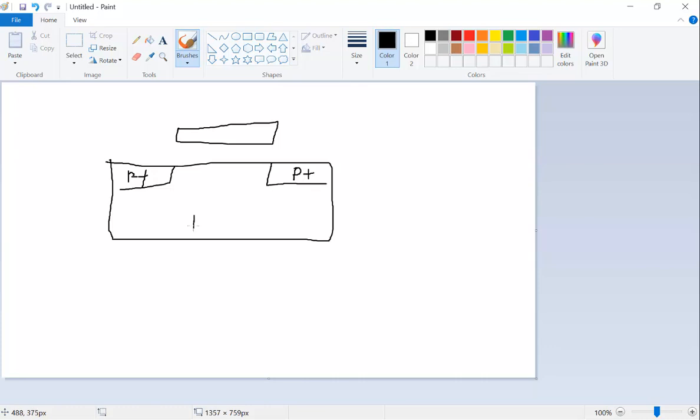And you're wondering, this is a P type. Is that shorting the source and drain to ground? Yeah. So you have to put the P plus in the N well. That's a process, right? To isolate it. It's not shorting to the ground because the P type substrate is always shorted to the ground, right? So the P plus of the PMOS has to be in the N well because the substrate is P type.